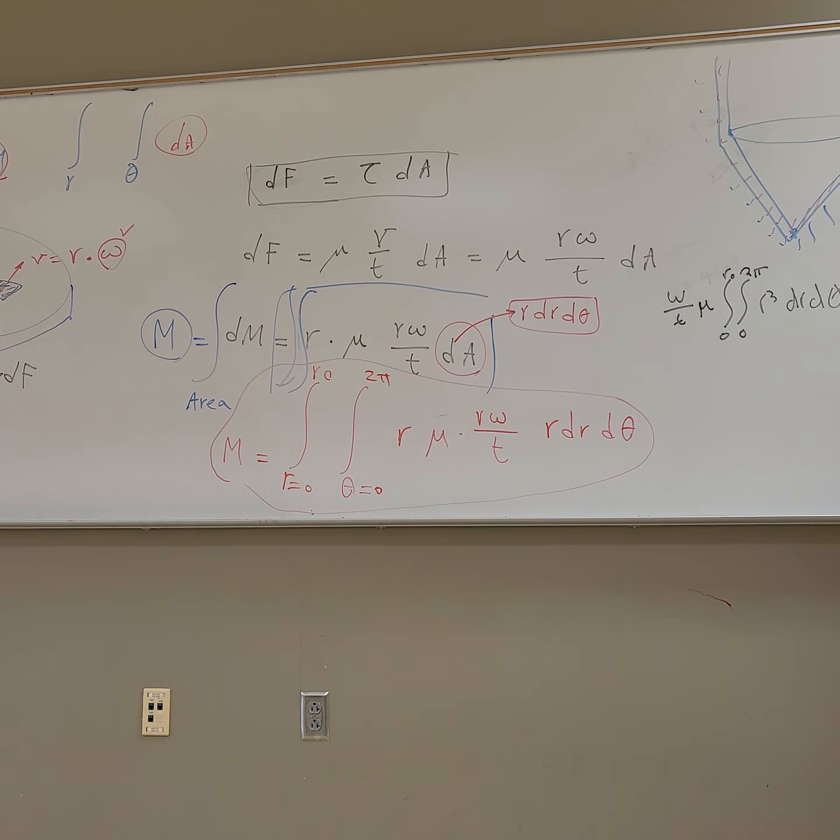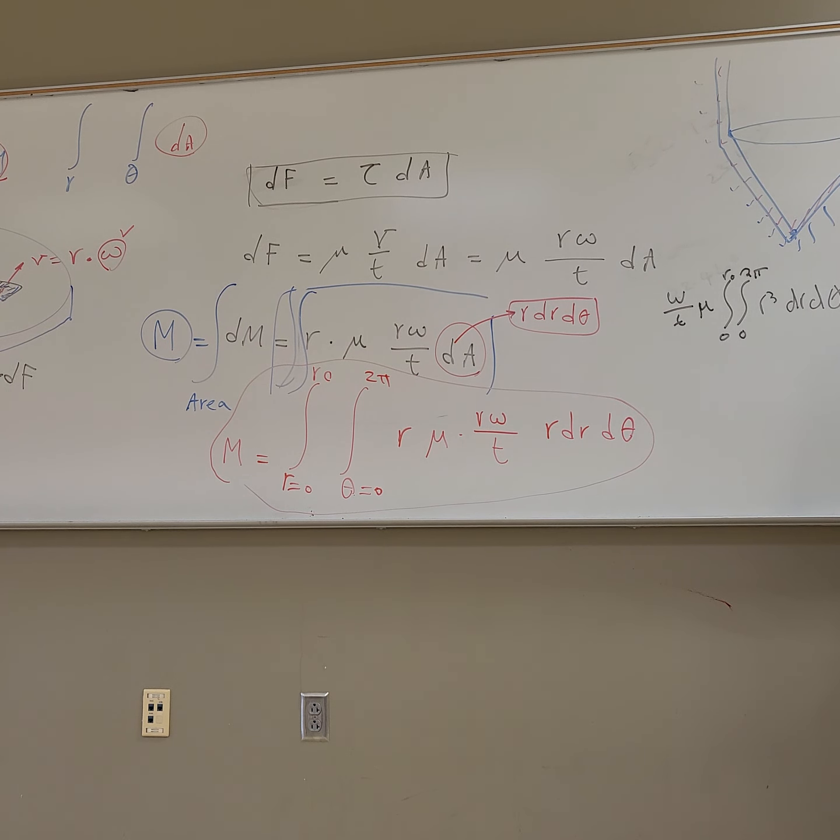If you want to do it more precisely, you should say RO plus RI divided by 2, because you assume the cutoff is between the outer diameter and inner diameter, since you go to the surface of the cylinder. So that problem is also posed. The way you can do that is to take the average, RO plus RI. But I didn't do that, I just did this, because that makes the equation very long.